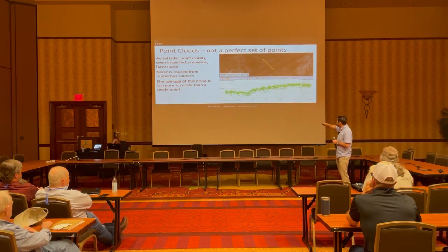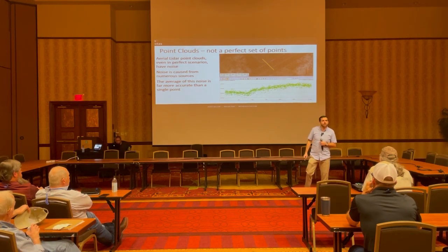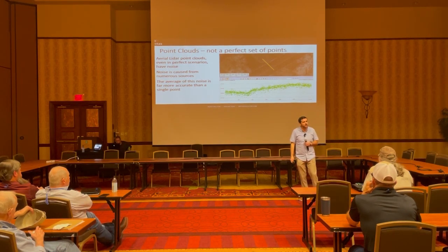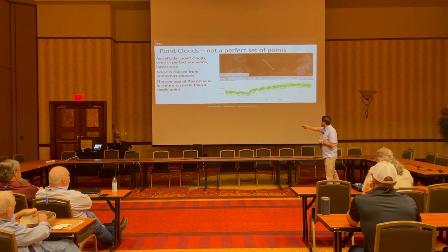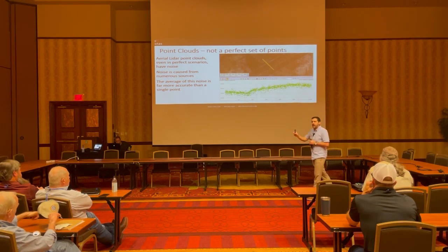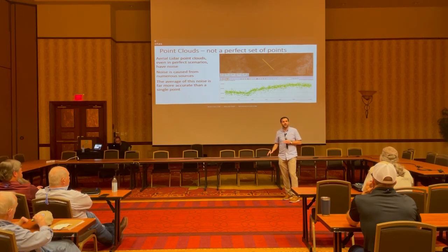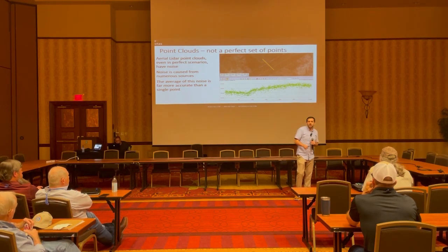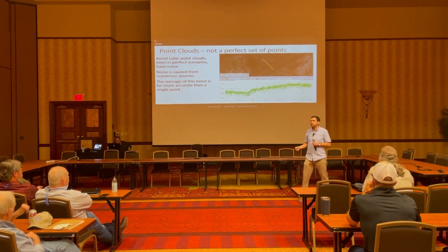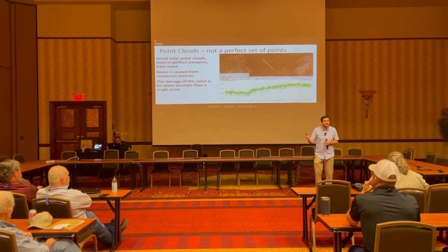And that means that each individual point that comes out of a LiDAR system itself should not be relied on because there is noise. However, if you were to draw a line through the center of that cloud, the statistical average of those points is going to be overwhelmingly more accurate than the point itself. This is a really cool technique that can be used so that the actual final survey data is more accurate than the sensor itself.